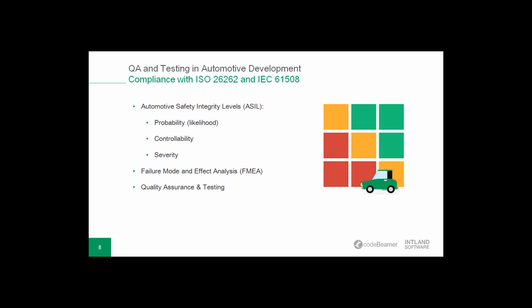The ASIL provides a method to determine each item's safety requirements. And these ASIL classes help determine the acceptable residual risk for each subsystem, as well as an acceptable general risk safety level.